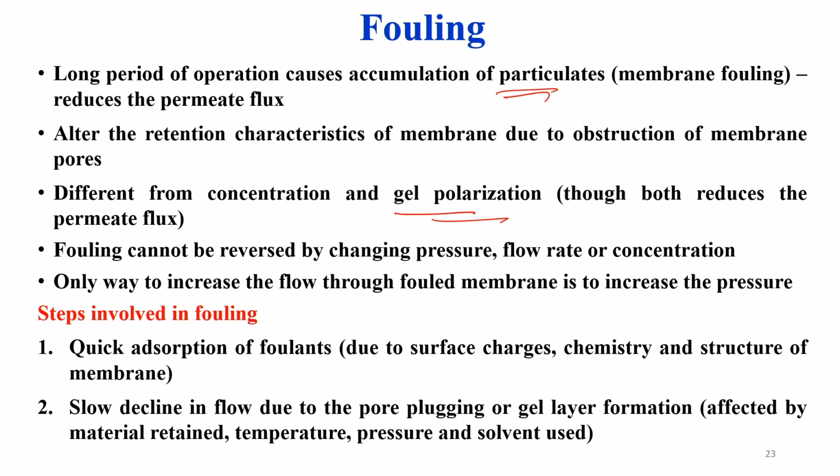Fouling is caused by foulants, it may be due to quick adsorption of foulants due to change in the surface charge, surface chemistry and structure of the membrane. And there is another reason, once this fouling is done, then there is a slow decline in the flow rate due to pore plugging or layer formation.